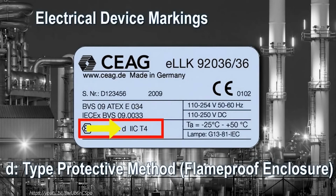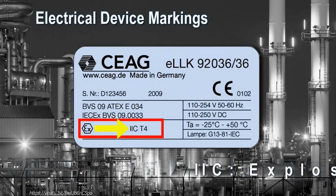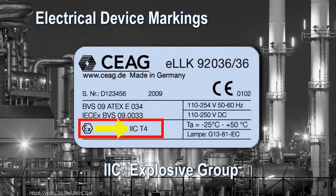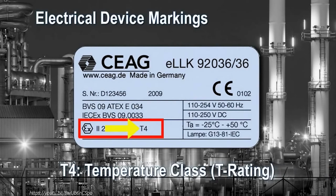Referring back, the letter D would suggest the electrical device utilizes a flameproof enclosure. The next number and letters will identify the explosive gas group. Remember, the gas group provides the critical information on the combustible material's explosive properties. The final marking provides the maximum surface temperature of the fixture during operation.